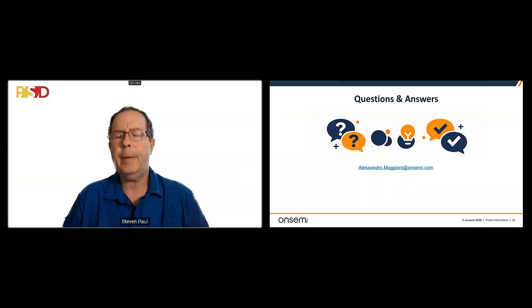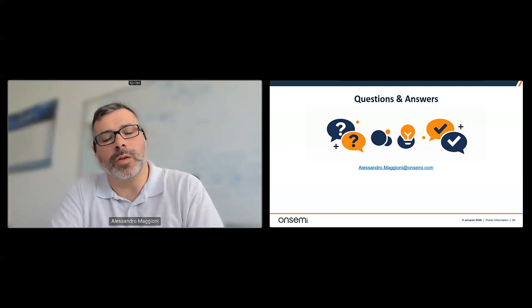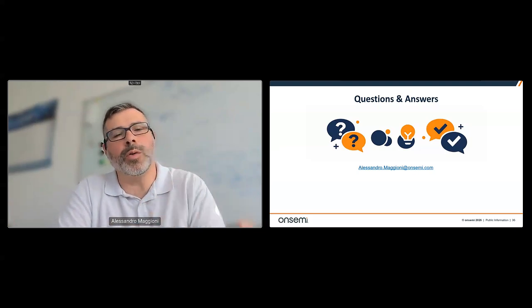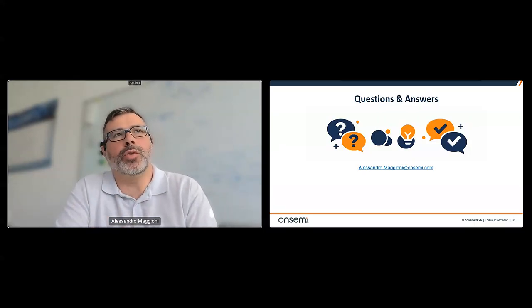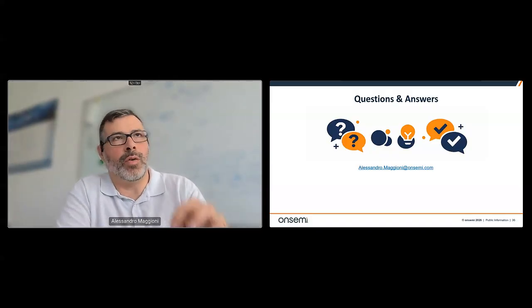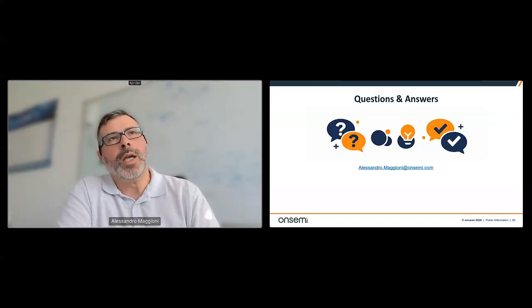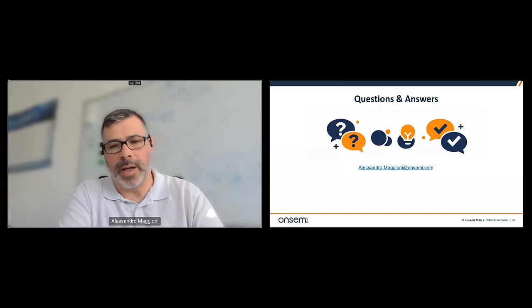Question here from Dennis: how does zonal architecture physically reduce wiring, and why is 48 volt central to it? Yes, as we saw at the beginning of the presentation, instead of point-to-point wiring for more than 100 ECUs, the vehicle is partitioned into 4, 5, or slightly more zones, each with a local controller and a single power feed, interconnected by automotive Ethernet, the high-speed backbone.